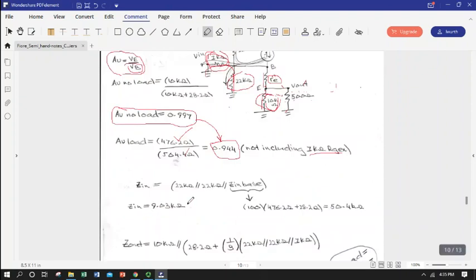So we'd end up reducing our system gain even more if we included that input. So hence why we want this resistor to be huge, because then we limit this current path and this stays high. And of course, staying high also helps us open the base emitter junction, so two jobs in one.